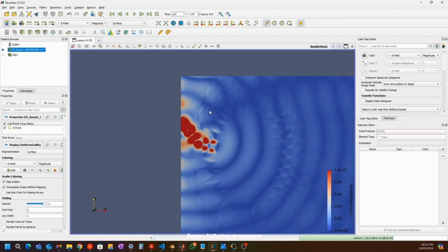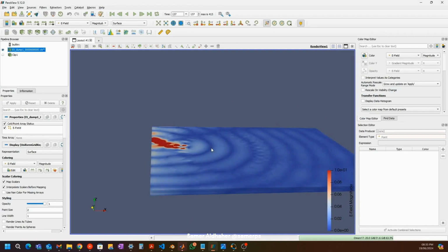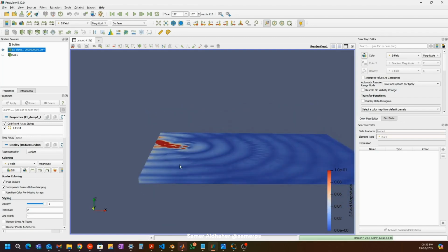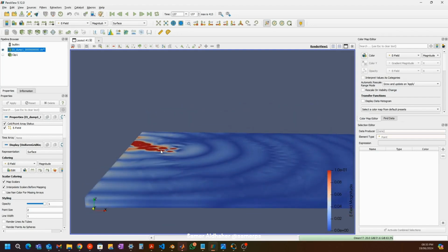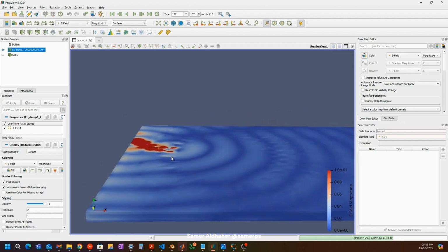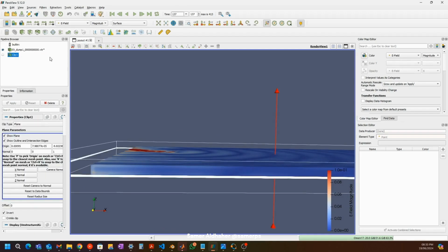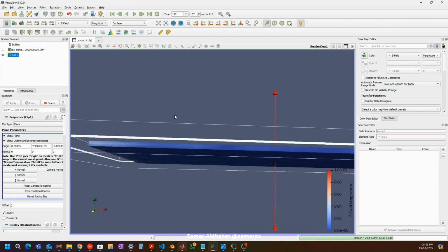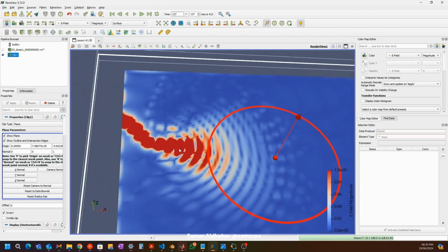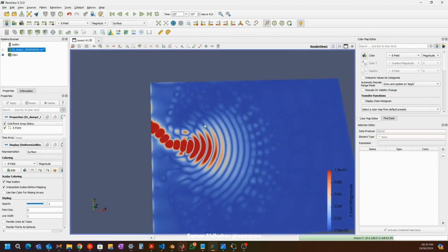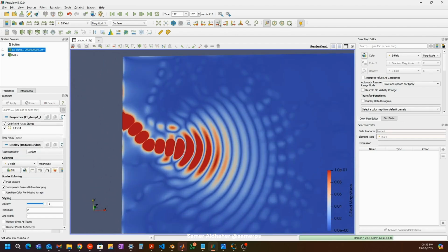Now, this is obviously viewing the E-box dump from the top. I would like to see the E field just above the PCB. I think for first visualizations, it's good just to see the E field inside the PCB, because that's where the waveforms are. So what I've done is I've set up a clip here, and let me just hide this. So now I can see the actual E field inside the PCB here. And I think this is a better image now.